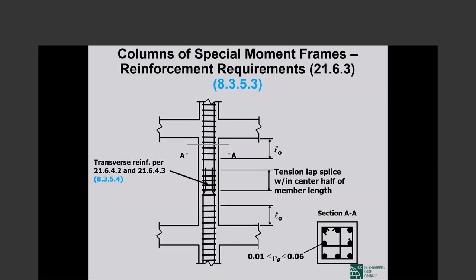The 3% is way high. I discussed that, I remember. 3% reinforcement in a column, you can place the reinforcement, but the problem, you have to think of the beam column joint, and let us try to visualize it.